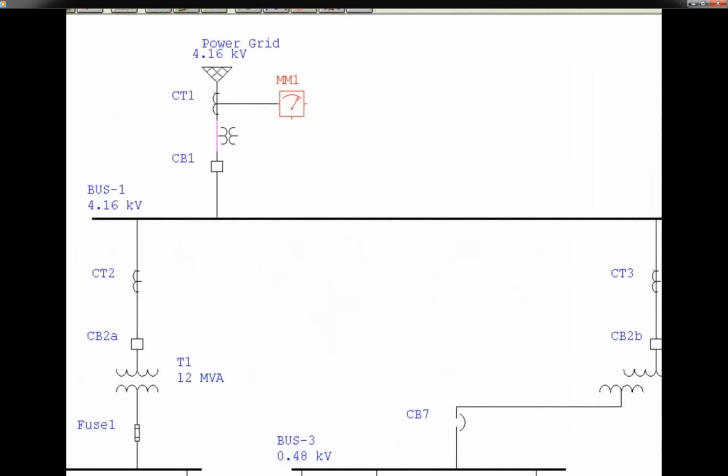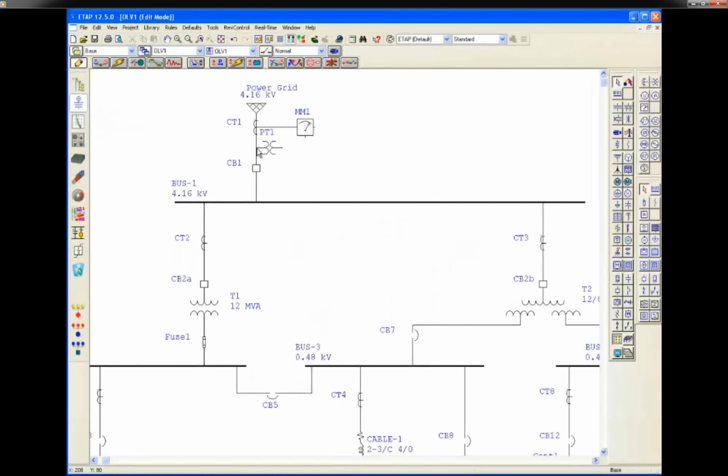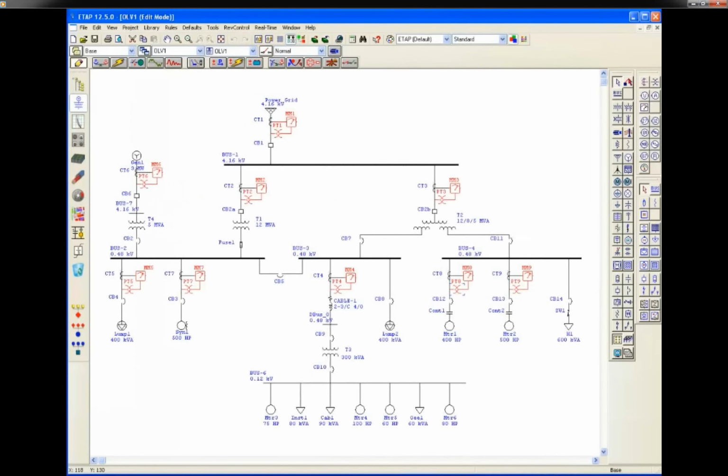Make sure any necessary current transformers and potential transformers are added to the ETAP one-line view and connect them to the multimeters. Here is the project after adding multimeters and potential transformers and connecting them to the imported current transformers. The multimeters will also require a tag file to be created for real-time applications. For more information, you may refer to the ETAP real-time video tutorials.